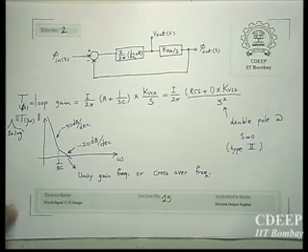So the trade-off which was there was system was not stable, and here now system is stable, and furthermore, because now you get better control on the unity gain crossover frequency, therefore you will be able to get better speed also.